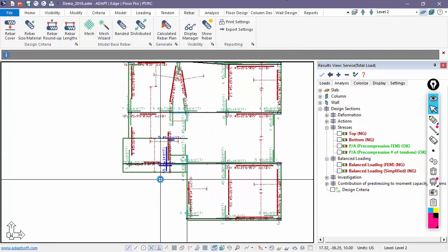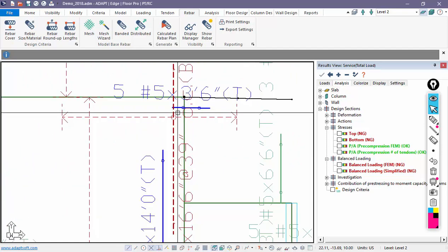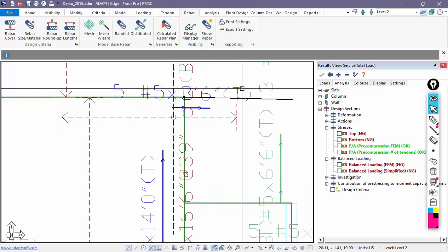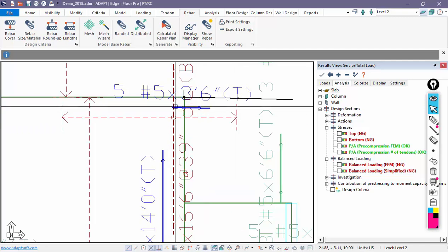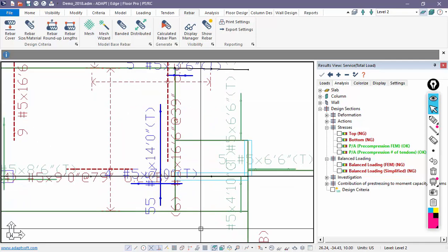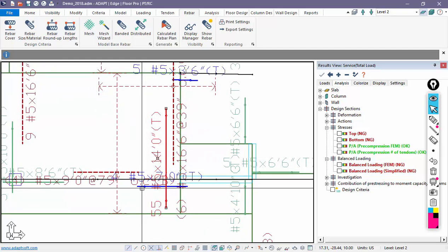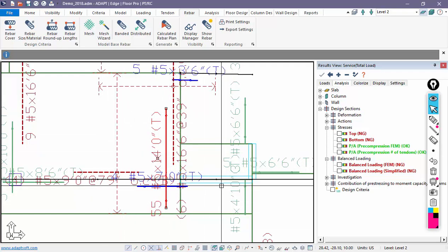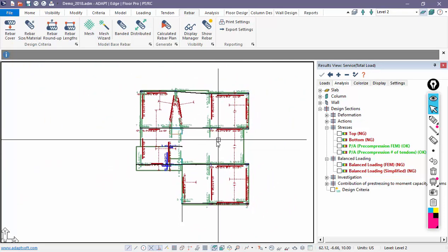The blue rebar just indicates that the piece of rebar is actually extending through different slab thicknesses. So this goes from one slab that's offset to one slab that's not. It's at the top of the slab, so it's mainly just a detail warning. This bar, if you're not careful, may stick out of the slab if you don't detail it properly, and that's what the blue reinforcement typically will indicate. This one here is also a similar warning. This is probably there because the distribution of 55 bars would go into one slab that's offset and one slab that is not.